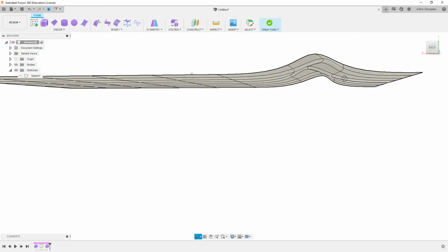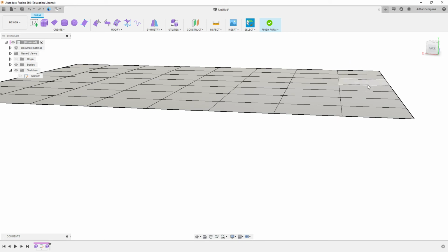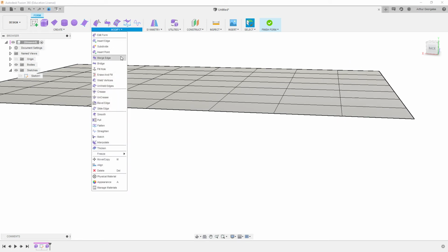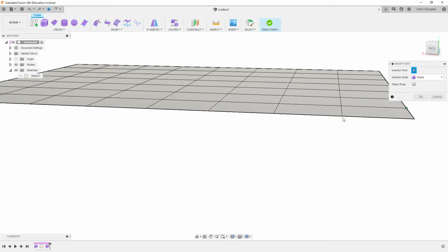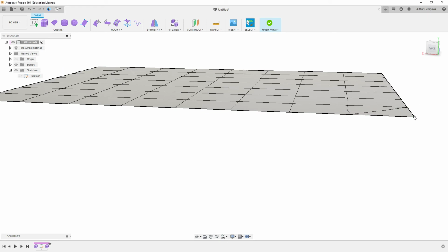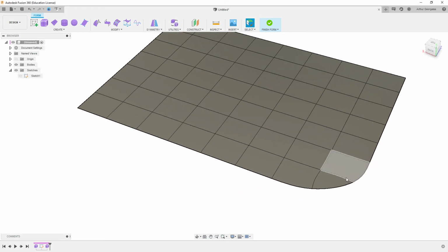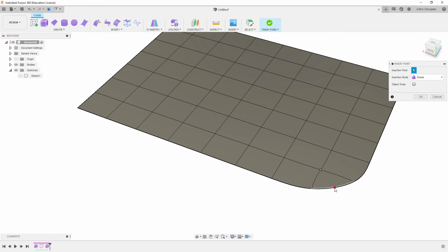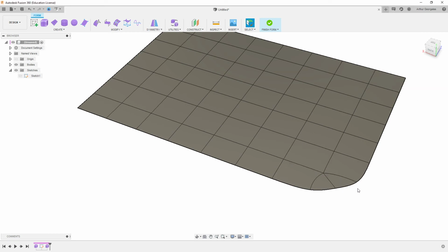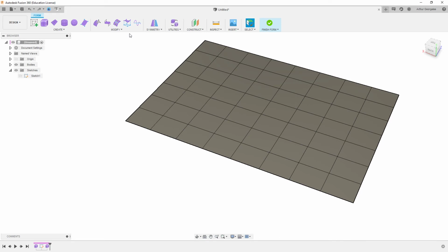You know, sometimes you want that, and sometimes just inserting things like that is really important. You can use it to change how the edges of your shape work. So if we go insert point from down here to here and delete that outside edge, it does round it out. However, we can see it is warped slightly. You've got to be really careful with how these work. I'm not a big fan of playing around with the edges like this. I would much rather try and get it as straight as possible and then fillet it later. But that is another use of that.